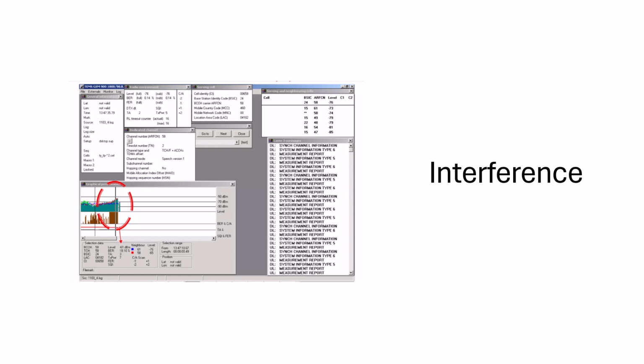If it is an unlicensed signal, adjust parameters like transmit power, antenna tilt, or neighbor definition to reduce the effect of co-channel or adjacent channel interference. If external equipment is causing noise, it may require locating and removing that source. By integrating frequency scan, drive test analysis, and knowledge of your network's channel assignment, you can pinpoint and address interference in a GSM network using TEMS.